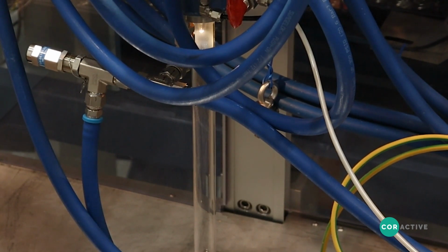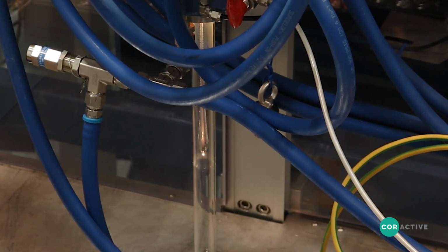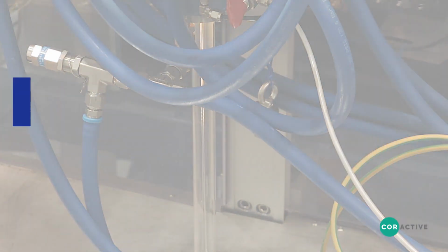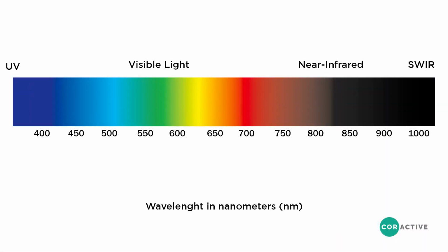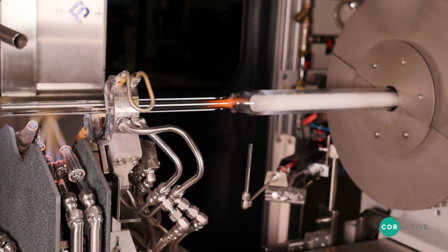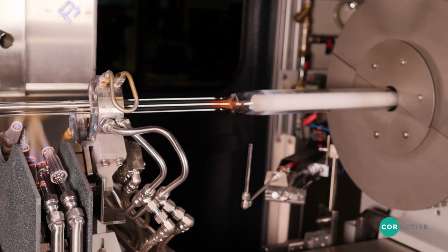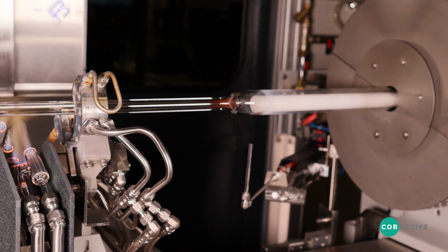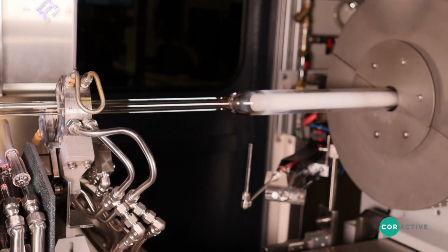Generally, optical fibers are made with glass as the primary material that is stretched into thin and long strands. They transport light, but they are not transparent to all wavelengths. Silica glass fibers have the best transmission window in the lower end of the infrared spectrum, in what is called the near-infrared and shortwave infrared wavelength bands. An optical fiber is never perfectly transparent. You will always end up with less power than what you started with. This is what we call the background losses.